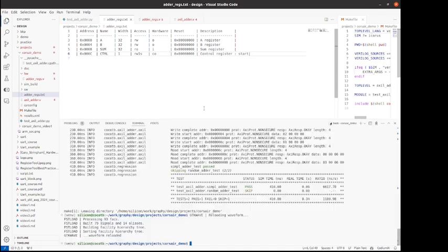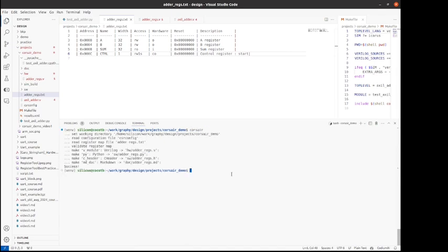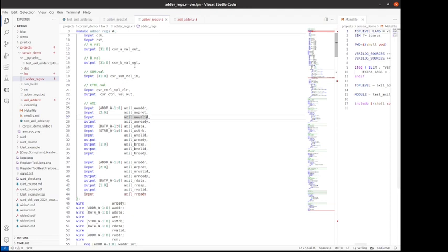Let us go and implement this register map. Then let us see what is created. So now we have, apart from A and B and some input and output ports, two more ports from the control. One output from the CSR, which will give the start, and from the hardware we acknowledge by clearing this port.